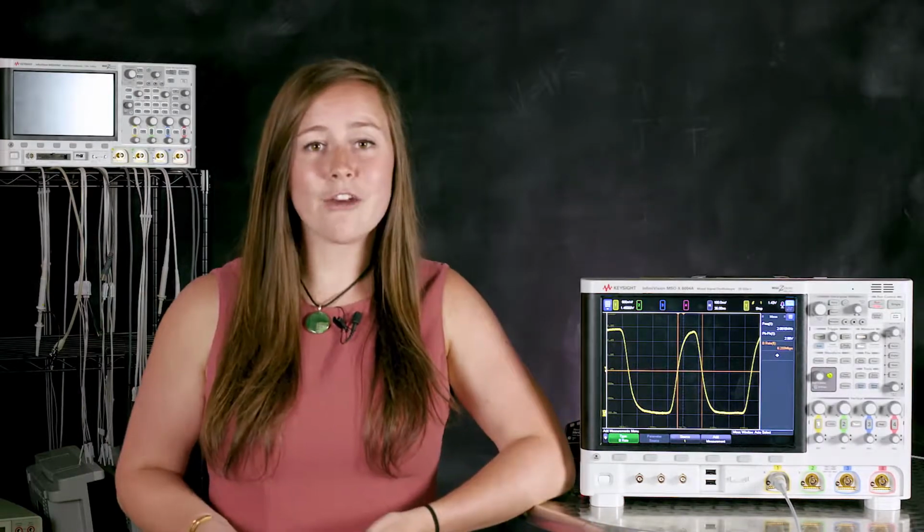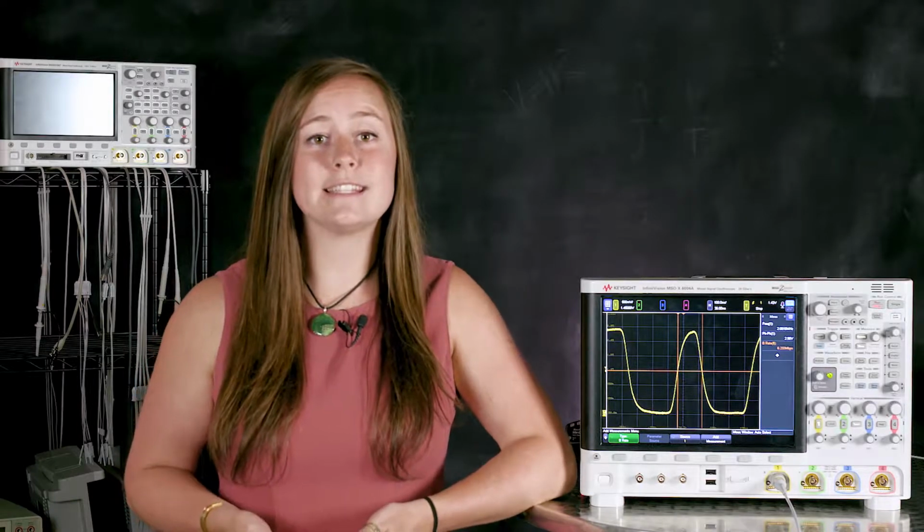Some signals use an explicit clock, which can be driven right into one of the channels of the scope. But other signals use an embedded clock. With an embedded clock, you have to have some way to de-embed or recover it. So that's when you use clock recovery. What the clock recovery actually does is calculate the exact ideal bit rate of the signal that you're working with. So let's take a look at some of the different clock recovery options that we have to work with.